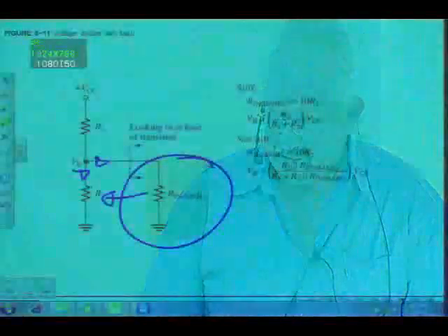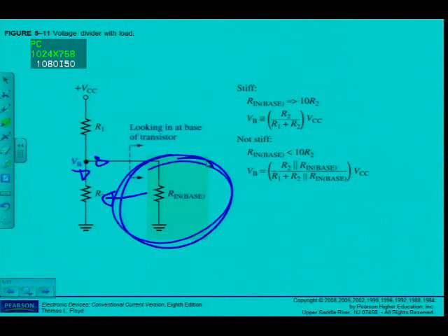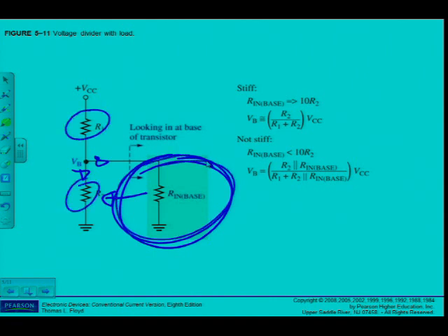Okay? So there's my voltage divider R1 and R2, and I can assume this R in base to compare with the circuit that I've just discussed. My voltmeter. So I have to go and check here because I can see that that resistance is in parallel with R2.